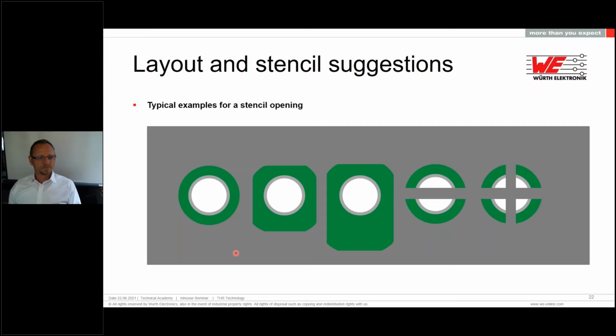And this can also be achieved by overprinting the solder paste on the PCB top side. A sufficient filling of the through hole and overfilling of about 1 millimeter inside the hole is very common. Yeah? And up to 30% of the paste volume can be overprinted. Here, we print directly on the solder resist.